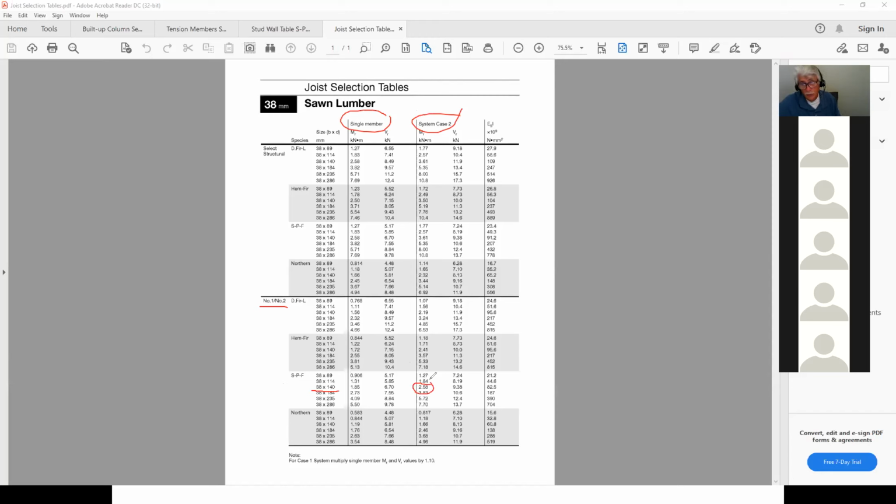Otherwise, use the formulas, guys. It's up to you. Now, because of the sheeting that's on the roof, and because it's going to be nailed at least no further than 300 millimeters on the intermediate supports and 150 millimeters along the edges, I'm allowed to take this value of MR from the table. It doesn't matter, you understand? It's MR. It's the resistance of the wood.